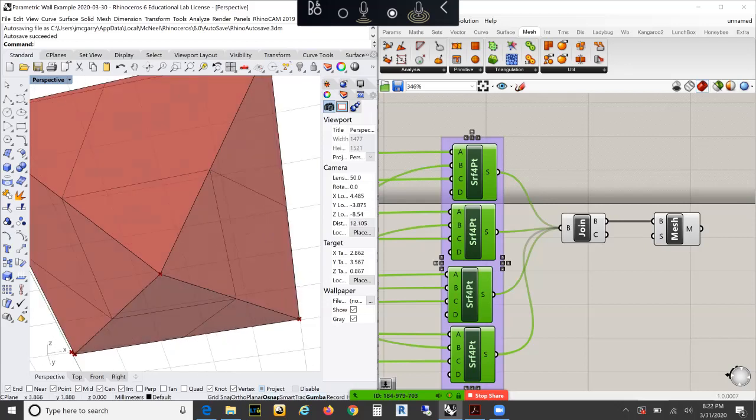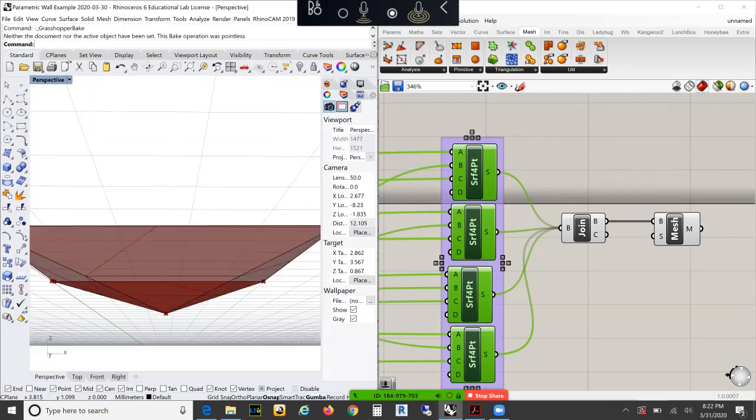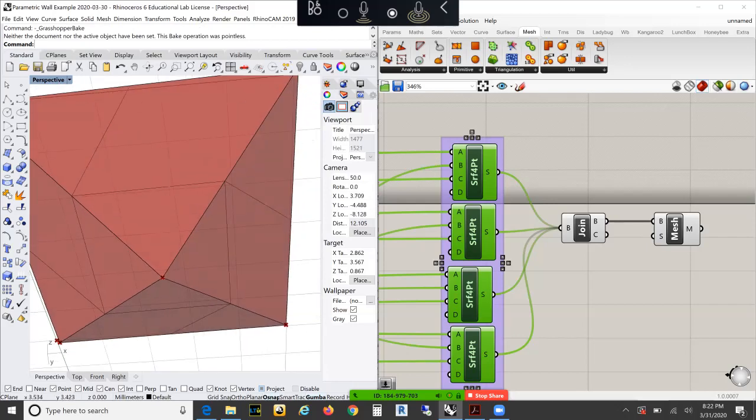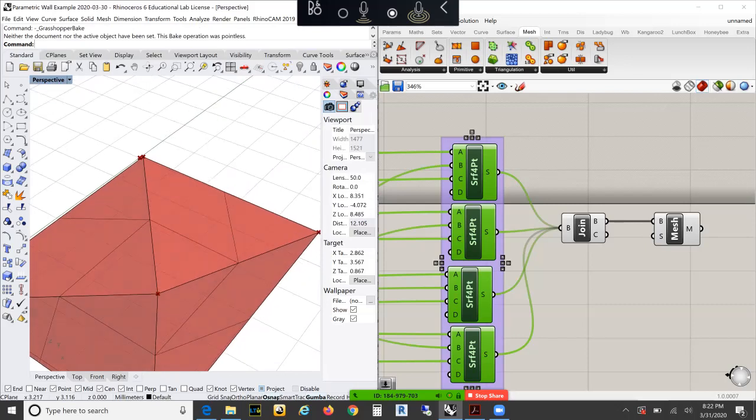Notice that all of these intersect each other. That's very important when we deal with meshes and Weaverbird, because we want these to intersect, since then they're going to create a nice smooth feel. If this had different intersections and was made up of many more faces than this, it may have a very different result, or it may not work the way that you predicted.